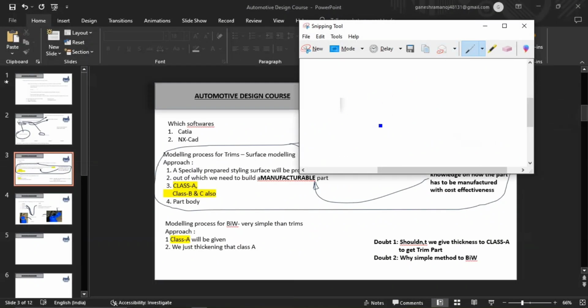Okay, so you have a part like this and you are pouring a molten plastic in this way. So that means the entire thing is an empty space. So you are pouring the molten plastic resin in this way. So that means your tooling direction will be like this, right? So in this way only, according to the gravity and all, this will go and set inside the cavity properly, right? So this is what we can know as the tooling axis.